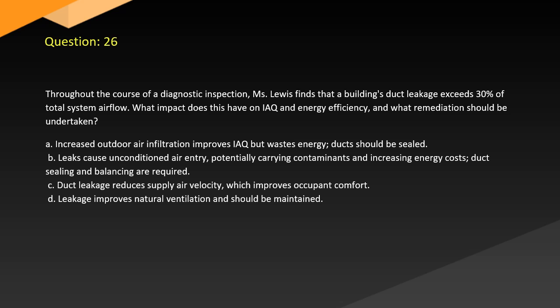B. Leaks cause unconditioned air entry, potentially carrying contaminants and increasing energy costs. Duct sealing and balancing are required. C. Duct leakage reduces supply air velocity, which improves occupant comfort. D. Leakage improves natural ventilation and should be maintained.